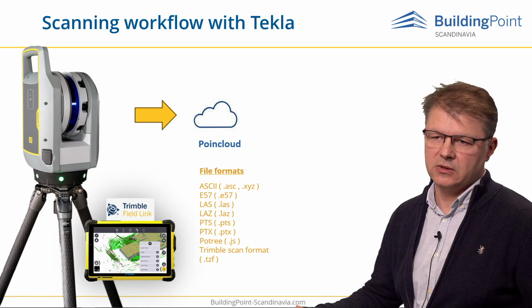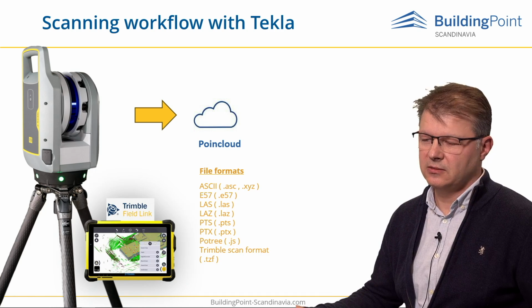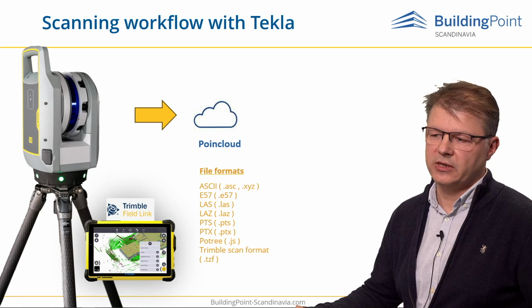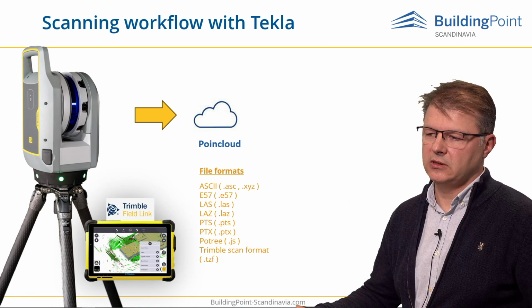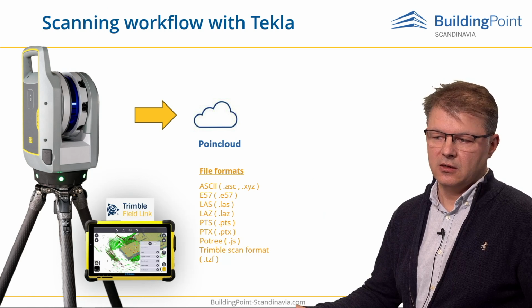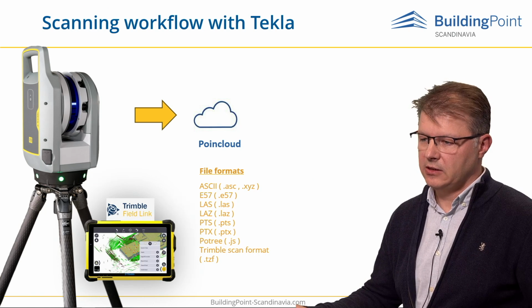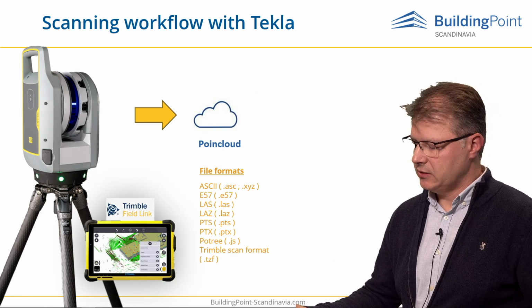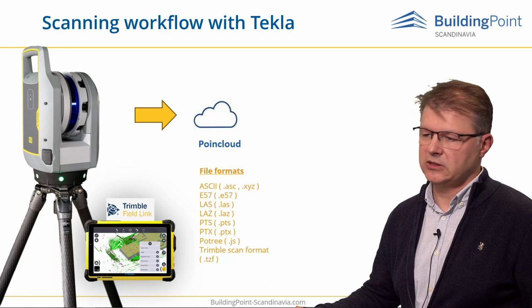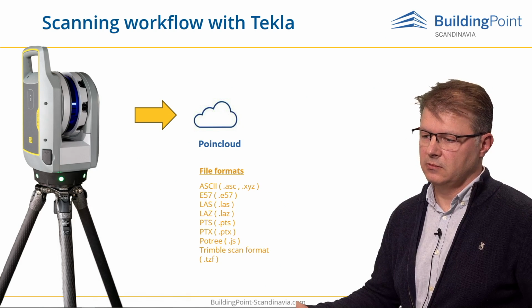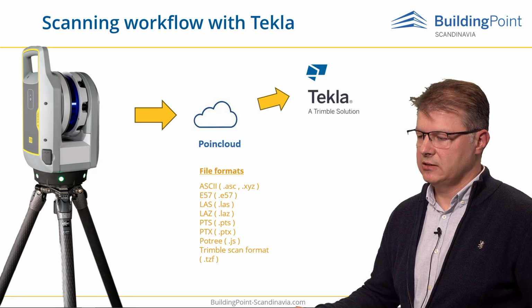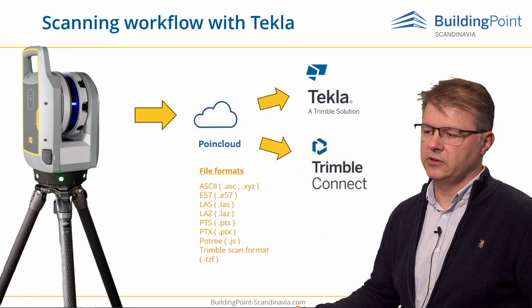What is the scanning workflow in Tekla? Of course, you need to have a point cloud. To do it, usually a geotechnician is going to create a point cloud on site using a scanner together with some kind of software which is connected to that. For Trimble, it's Trimble FieldLink, but for Trimble scanners, it's so simple that you don't even have to use the tablet. You can just use one-click functionality to create the point cloud. As simple as this. When you have a point cloud, it's very easy to send the point cloud to the cloud or directly to Tekla Structures.